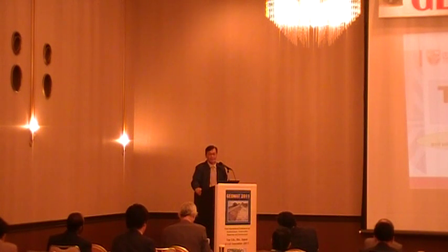One, the pole acts as a shear pile. Secondly, you have the roots, which improve the soil. And third, you have the added benefit of the suction. But of course, the live pole is only used for shallow stabilization. It's not good for any kind of deep landslide. But for surface landslides, shallow landslides, it is a good technique.